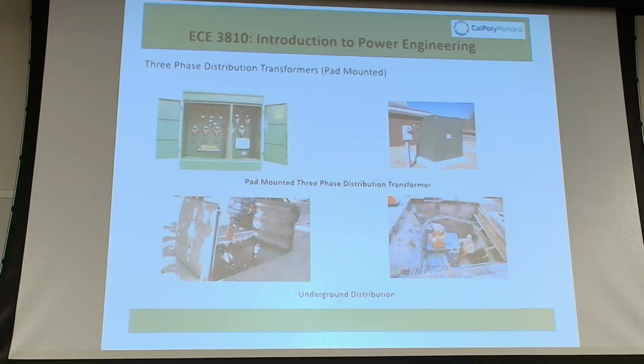Oh, yes, I forgot to mention, these ones are dry type. There's no oil on them. The only way this cools is with ambient air, no forced air, no fans, nothing. And hence, the casing is a lot larger because you need more surface area to cool them off. The ones on the underground, the submersible transformers, those are oil filled transformers, because cooling is not as easy. All right.